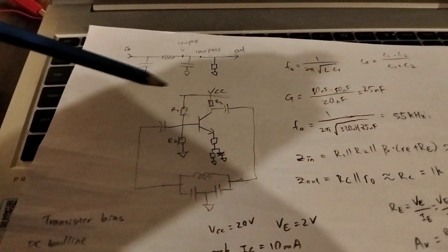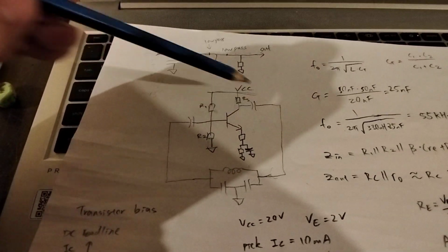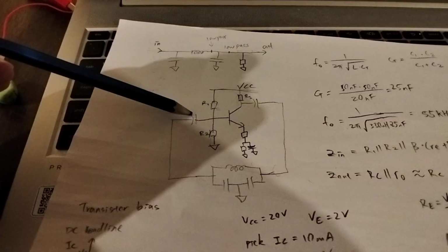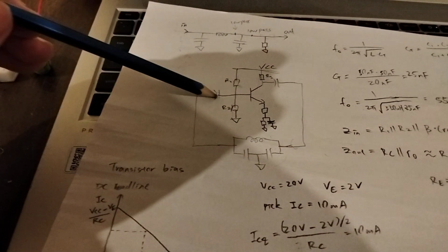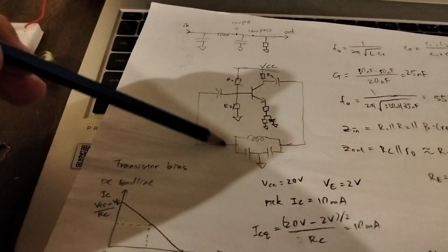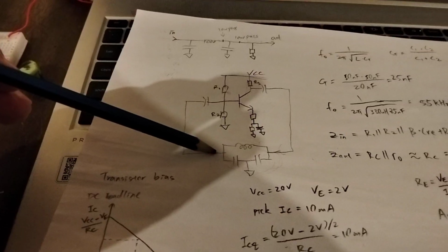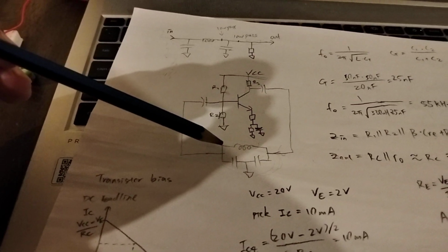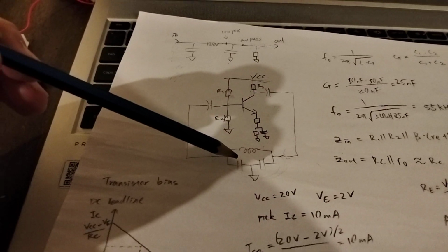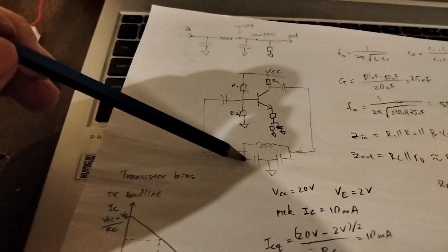There are a few things here, right? For example, the coupling capacitors also introduce a phase shift. The phase shift introduced by those has to be offset by whatever phase shift is in the LC tank filter in order to achieve 180. And obviously, because I'm using cheap Chinese components, these capacitors are not exactly as stated.